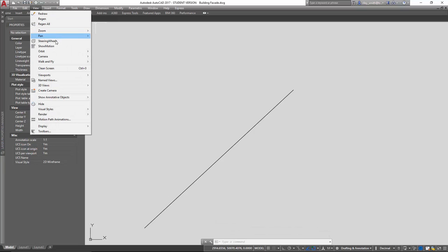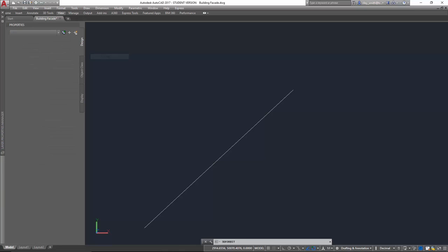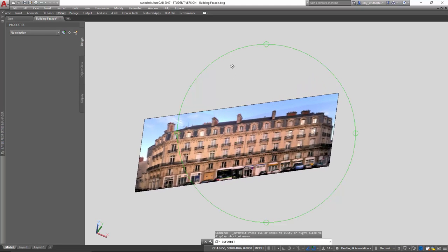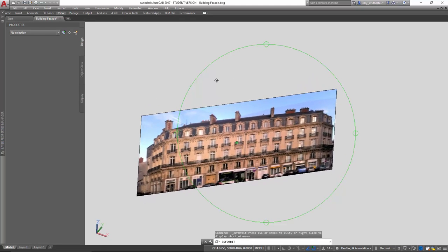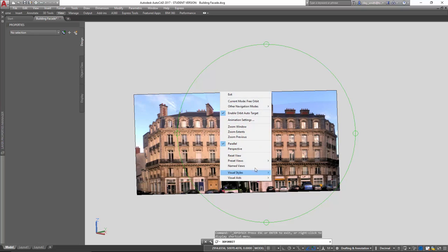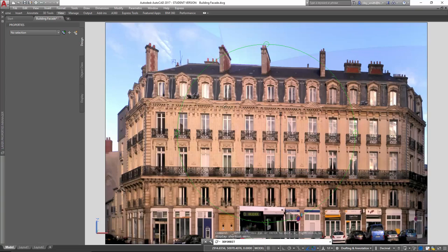If you go into the 3D view and pan around, see here's our ortho rectified image, and now I can use that. If I go to the front view, now I can see the image, and I can also perform drafting and deliverable creation here. This concludes a demonstration on the ortho rectified image command, now in Trimble Business Center version 3.90.